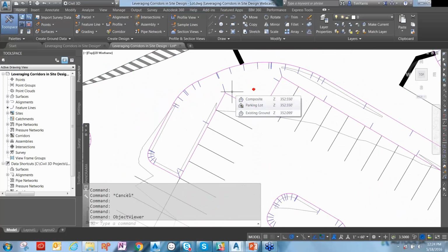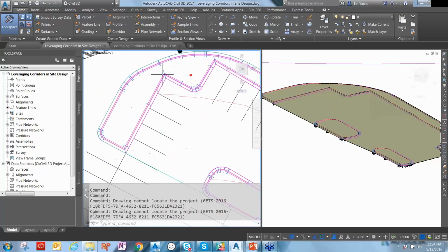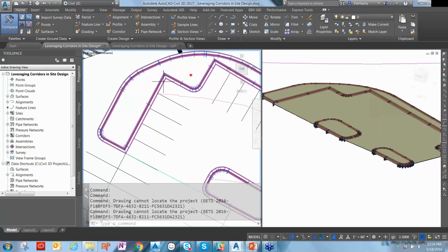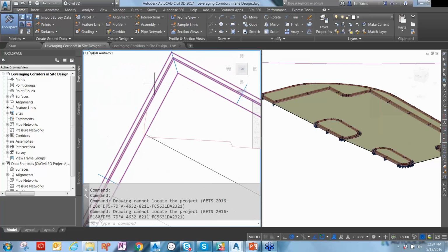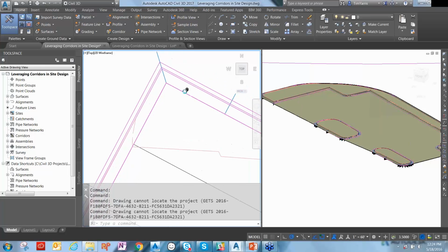One of the caveats with the bow tie cleanup right now, which we are doing a bit of research around, is that it only works on fixed width links. This is a case where the particular assembly is consistent: the top of the curve, the width of the gutter, and everything over the length of the baseline is always the same, so that cleans up quite nicely.